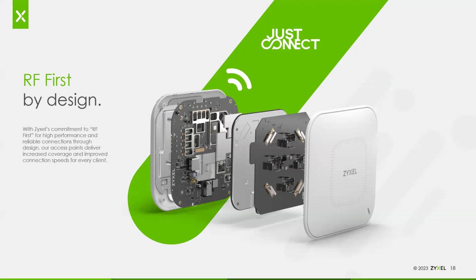When you're dealing with solid state technology like access points, one of the leading causes of failure is heat fatigue. Basically, heat builds up, you get heat cycles as things heat and cool, and you can have problems with the individual little micro switches that are part of microchips. Those can fail, solder joints can crack. To combat this, you'll notice that all of our access points have a lot of vent holes on them to allow heat to escape the case.